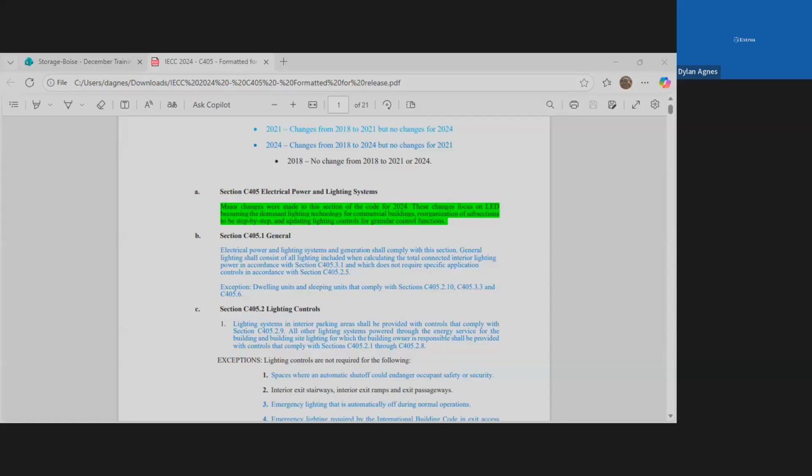Gotcha. So the incandescents were using full wattage originally as opposed to that. Yeah, and also heat, you have to deal with that. If you had a building using 2x4 T12 fixtures with 3 or 4 bulbs, and you multiply that one fixture by 400, now you've got a heat load you have to deal with. One thing we found is if you retrofit that building and replace all 400 fixtures with LEDs, now you have to rebalance your HVAC system because your heating load is now different.